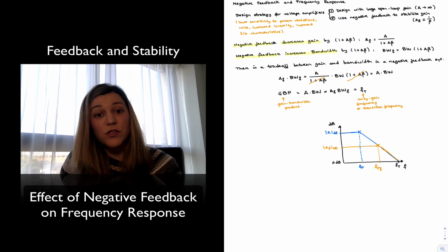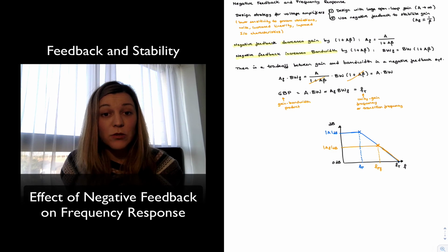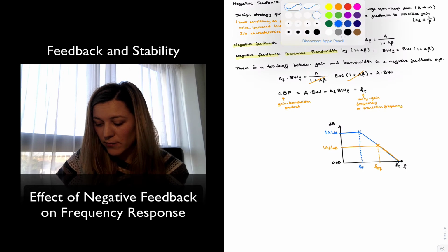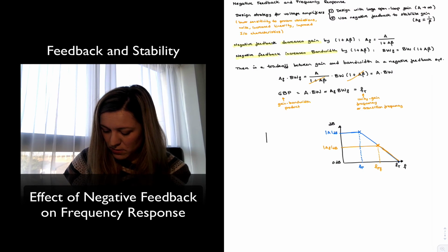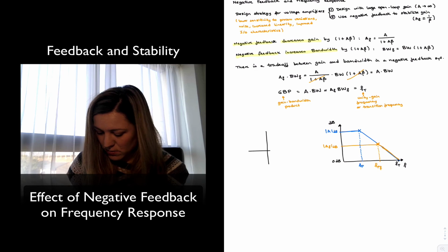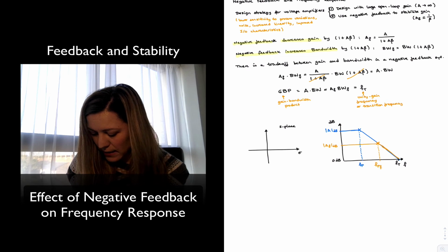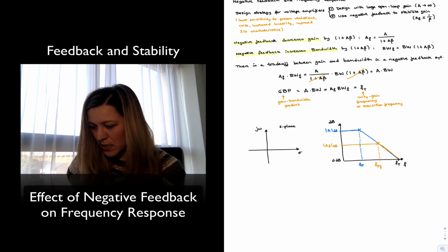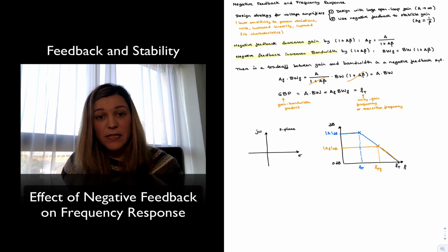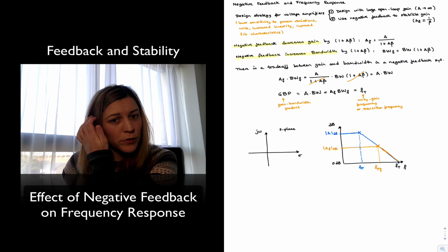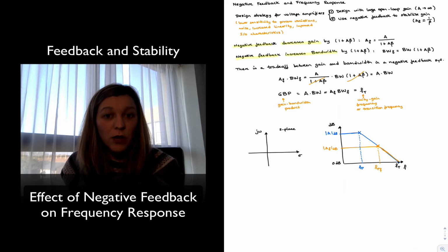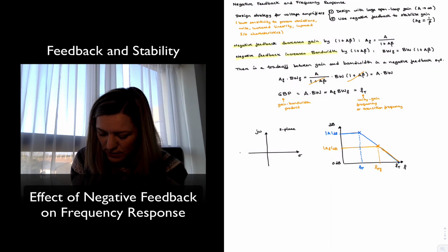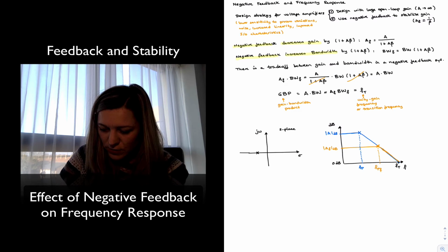If you wanted to see what's happening, just for a graphical tool, in the S-plane, the complex frequency plane, where you can do your root locus analysis. So if this is my S-plane, this will be my real axis, this will be my imaginary axis, and in this case, I have a single pole. It's got to be a real pole because imaginary poles come in complex conjugate pairs. And so in essence, I will have a real pole, and initially it was located at a certain frequency.